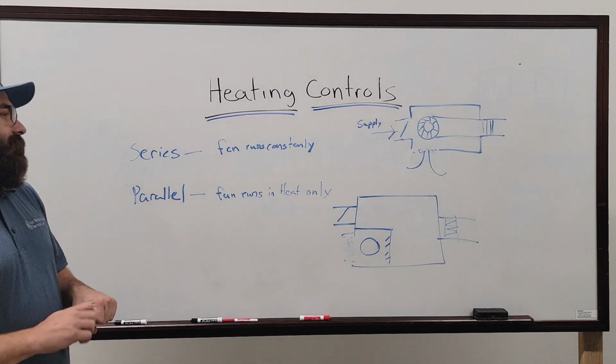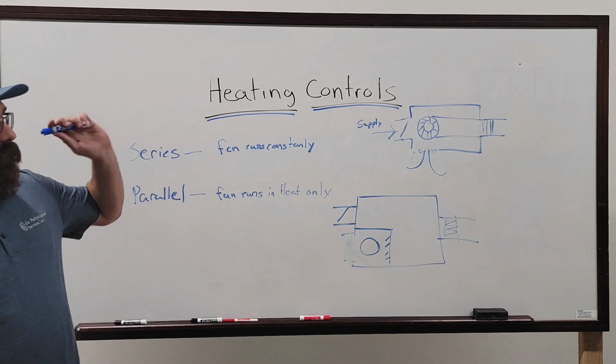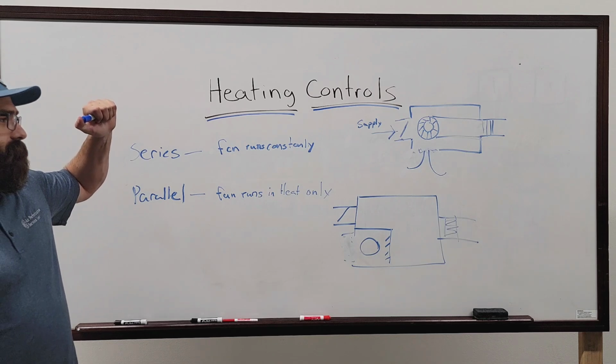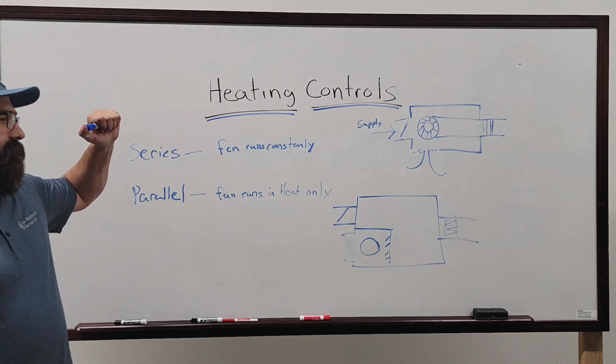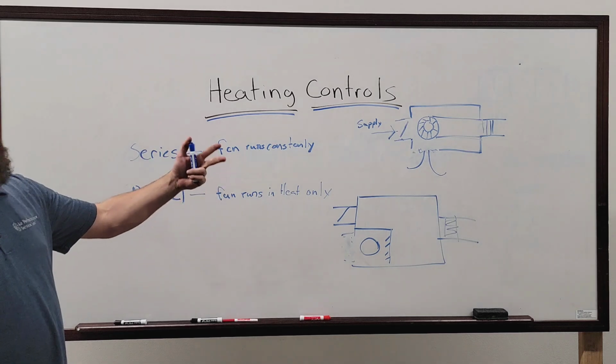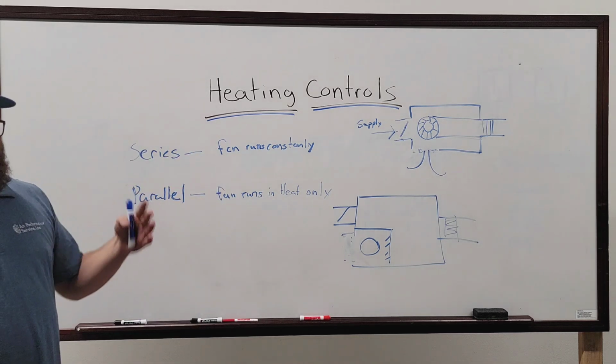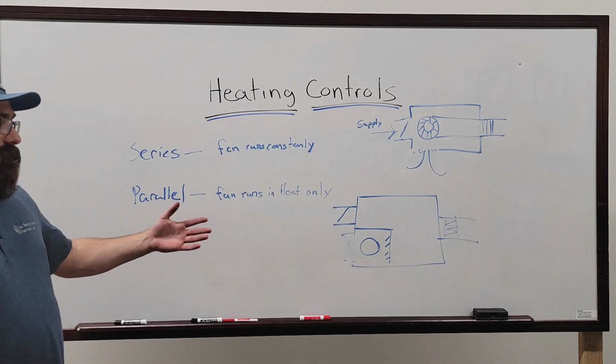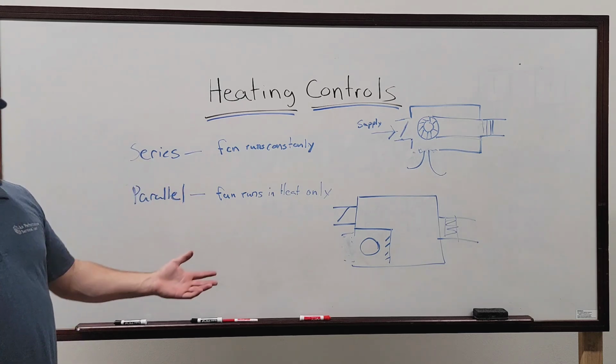But yeah, so series box, your fan will always be running. Think of it kind of as, we'll just call it a mixing box, right? You're constantly mixing supply and return through a series box. Parallel is pretty much either or.